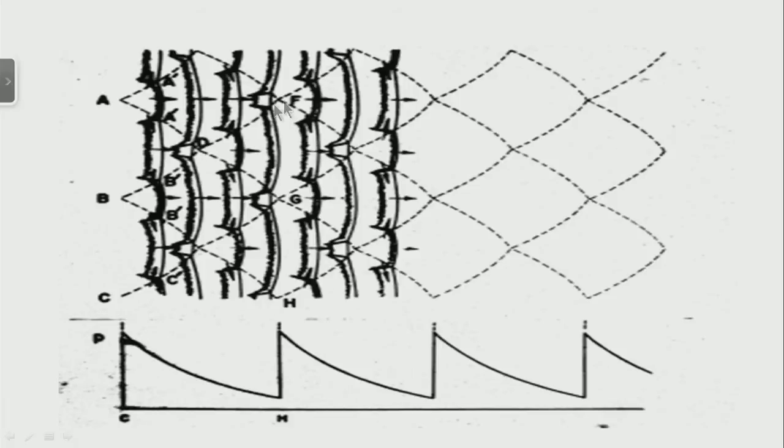If I were to consider events within a single cell, this cell followed by the next cell of detonation followed by the next cell of detonation, what is it I get? I get, at the point of intersection of the triple points, that is the two transverse waves intersect, all of a sudden an increase in the Mach number from a mean value to something like 1.2, 1.3 times the mean Mach number, and within the cell the Mach number keeps decaying, it reaches a value between 0.6 to 0.8 times the mean value, and again it spikes up, again it drops in the next cell.